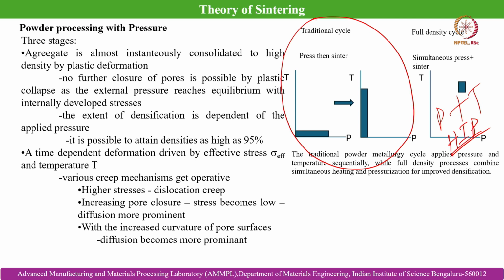So, in the case of sintering, there is a time dependent deformation driven by effective stress sigma effective and temperature T. In this case various creep mechanisms become operational. At higher stresses, dislocation creep operates. With increasing pore closure, the stress becomes low, and with the increased curvature of pore surfaces, diffusion becomes more prominent.